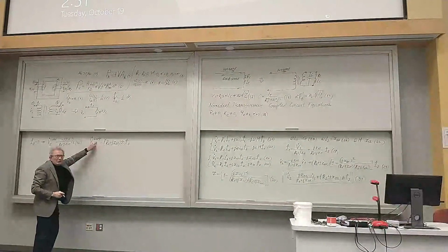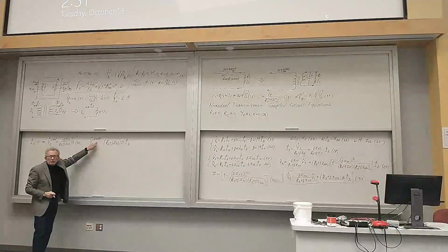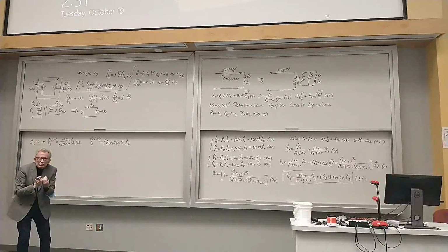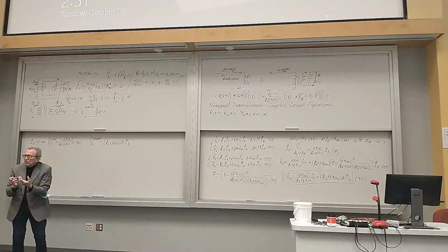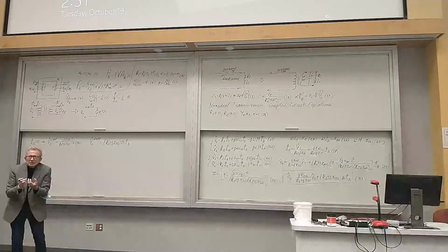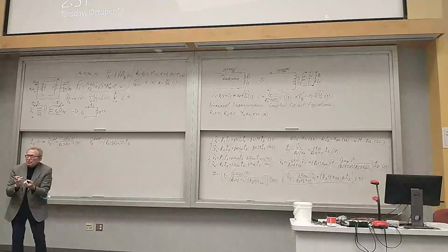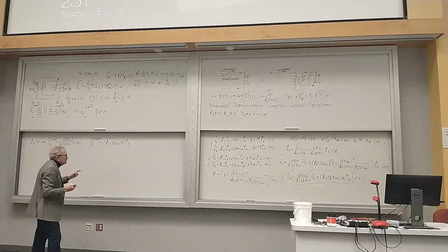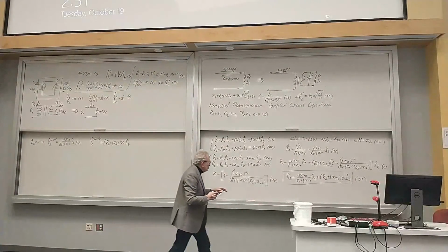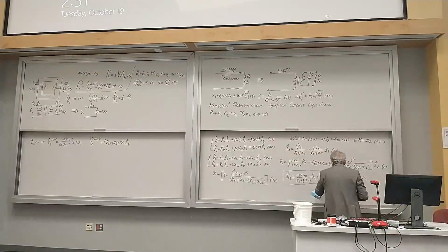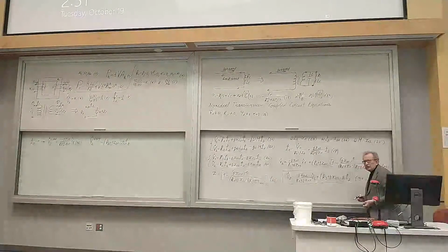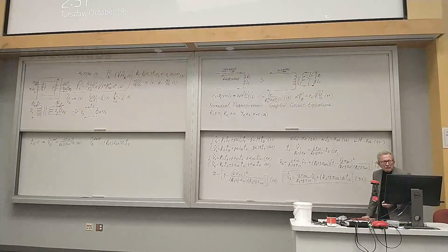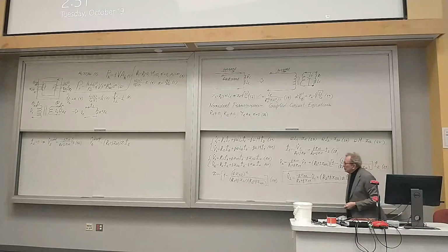And I put here the superscript drop. What does it mean physically? That represents the drop of the voltage due to the load. The load results in some current, and consequently the voltage across the secondary winding when there is a load is not equal to the induced voltage. It will be this term, which is due to the load current I sub 2, and consequently an additional drop of the voltage.